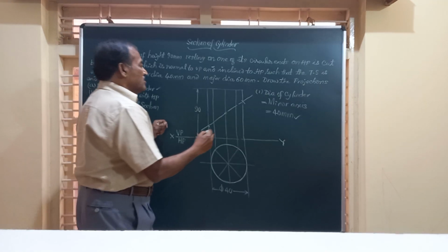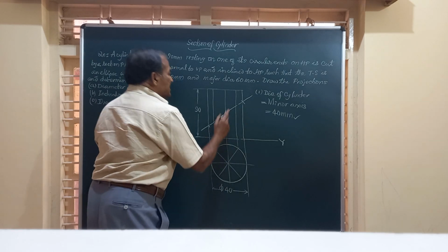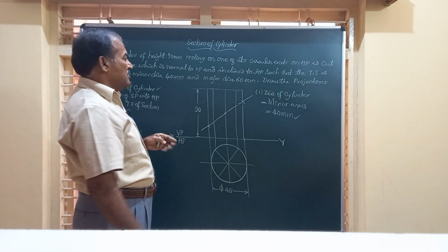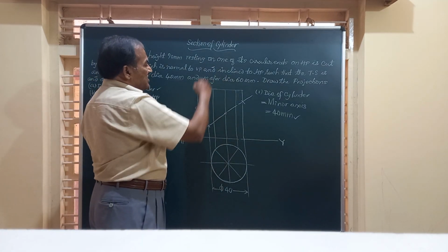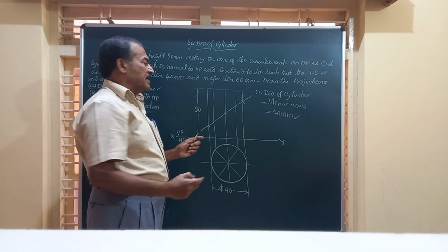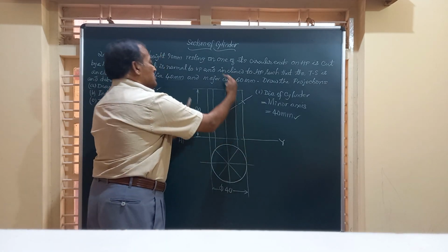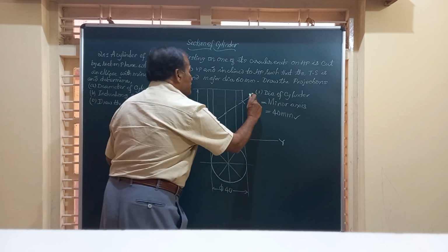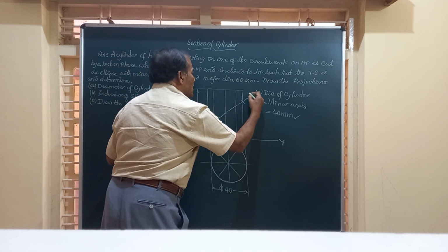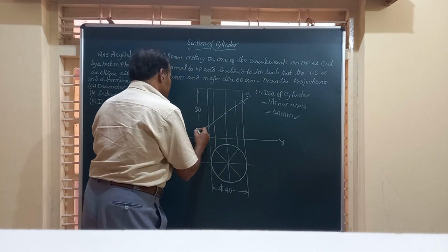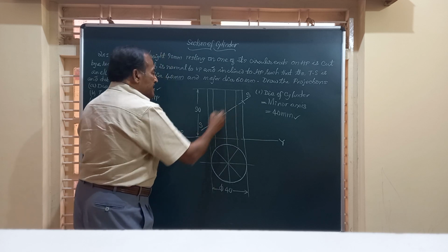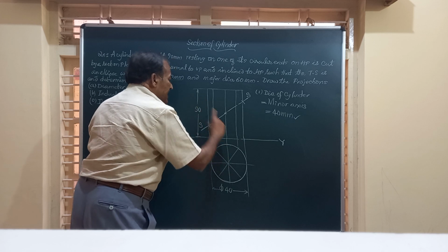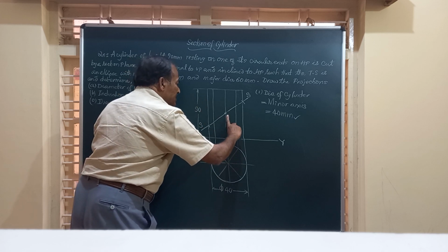30 millimeter. So this is 30 and this is 30. So in the mirror image, that is the true shape of the section, you are going to have the major diameter of the ellipse as 60. That is equal to this value. Now friends, this is the section plane we have got, and I will call this section plane SS, and it is passing through the mid height of the cylinder at a height of 45 millimeter from here.